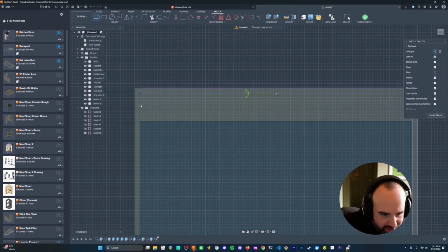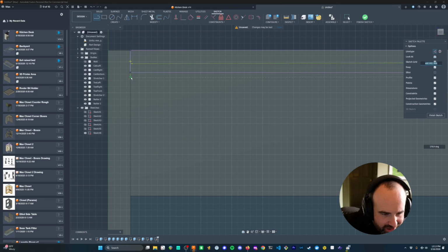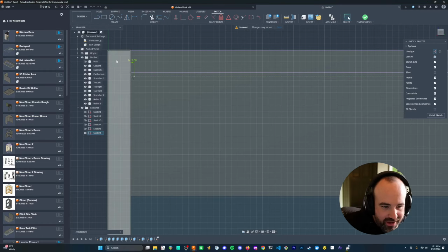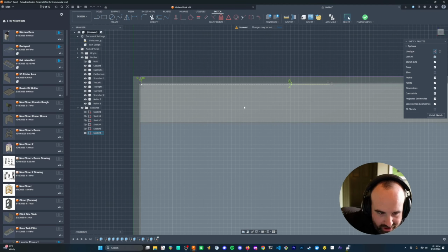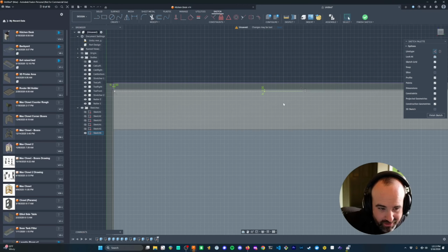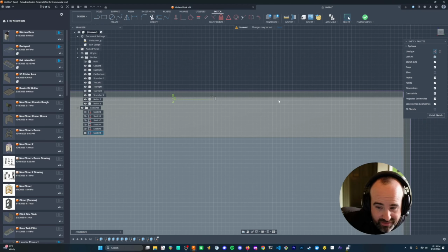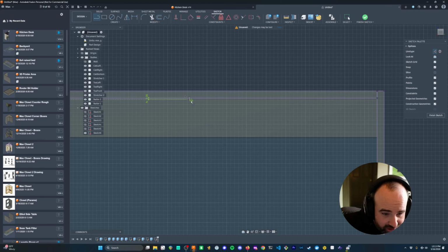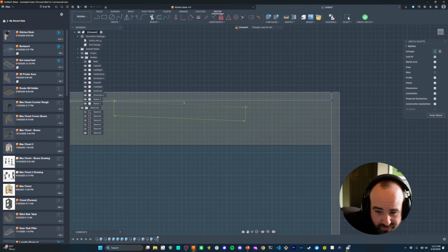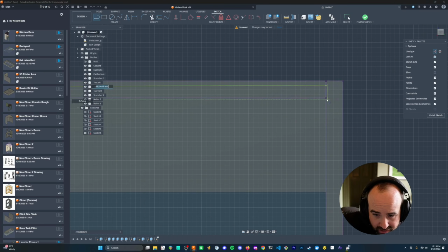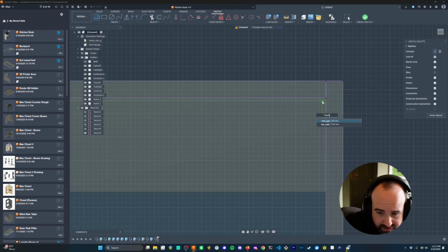Then I draw a starting point over to the other side, and another line that's also the inset gap. I'm trying to give myself a way to draw a rectangle that is the drawer front, using these gaps as a reference. I'll do the same on the other side: I draw a line over to the other side, and draw another inset gap out.